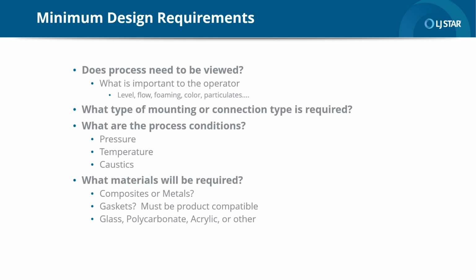In most cases when we get a job from an engineering firm, we're going to have a minimum, we're going to have a maximum, and we're going to have an operating. And in many cases, it's interesting because we can easily achieve the operating requirements. It might be something simple like 20 psi at 200 degrees, but then they're going to have a maximum, normally a worst case scenario, and it might go to 800 degrees and 150 psi maximum.